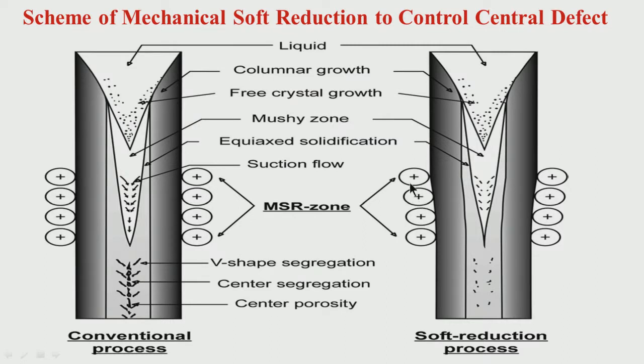That is why the pressure, the strain formation, is gradual. You are not putting a sudden pressure at any point of solidification. You are putting the pressure slowly. That is why it is called soft reduction, and that too, there is a gradient of reduction. It is not one step of reduction; slowly it is increasing. As such, the total reduction is not much, but there is a gradient, that means slowly it is increasing. So, this is an important concept.